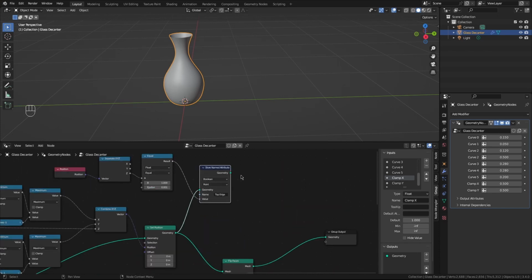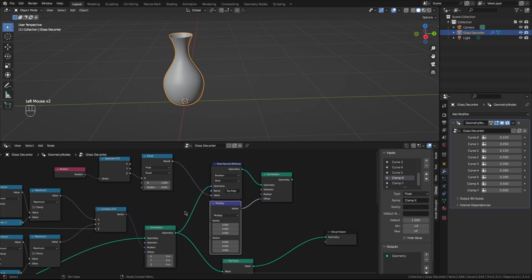Now let's go ahead and scale this out a bit. I'm going to do a set position. We're going to move each position outwards along the face normal. Now, I could move them inwards just as easily to create a thickness, but on the inside of the bottle is going to be the liquid. And it's easiest if I start with the inside surface of the glass, I expand it to make the outside surface of the glass, and also I contract it just a little bit to make the liquid, then everything lines up nicely. So we're going to move this out.